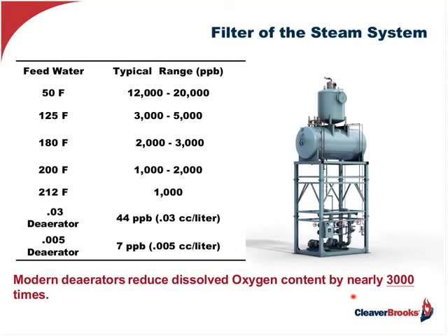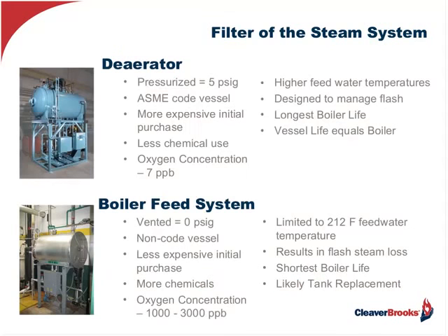That's why we use deaerators. They feed the boiler. They capture the hot condensate, and then we drive off those corrosive gases, oxygen and carbon dioxide. So if we take a look at the differences between going with a feed system versus a deaerator, the only negative of a deaerator against a common feed system is it's more expensive.